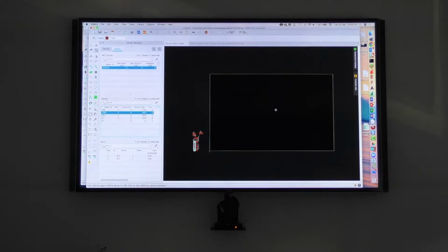And then he contacted me and the board manufacturer, and together we figured out how to set up minimum clearance values, minimum wire widths and so on. And now we have a 2-layer board. And that's something you have to start thinking about in the beginning.